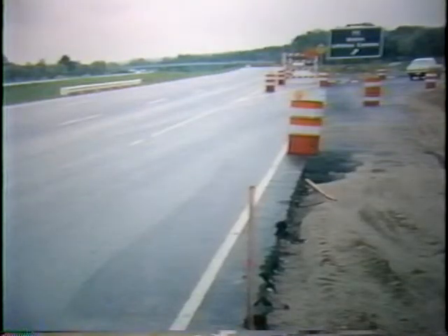Raveled pavement edges cause steering problems when a wheel drops off the pavement. Because drivers stay away from raveled edges, the effective lane width is reduced. Structural problems in the roadway will also be created.